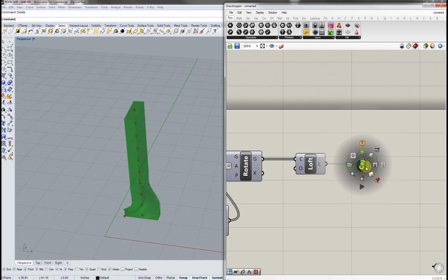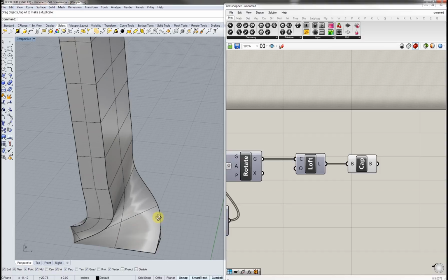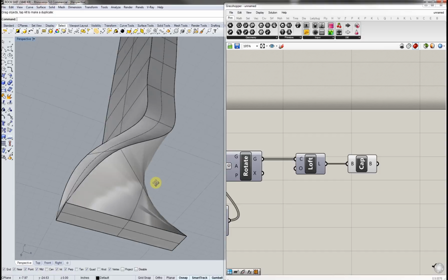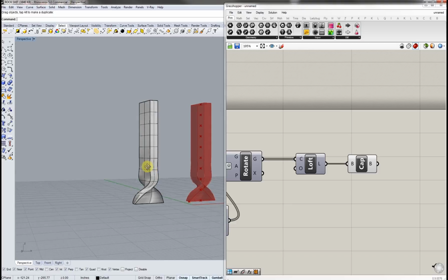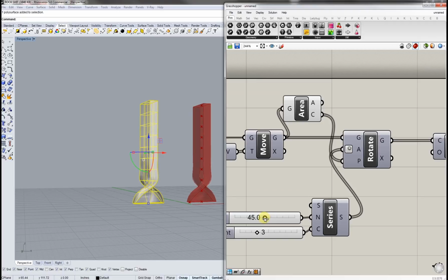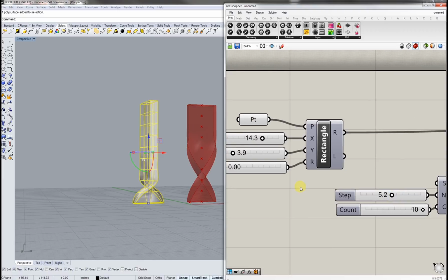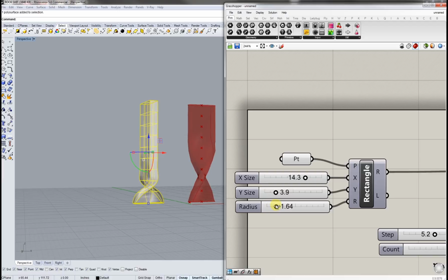Now, if you wanted to select this geometry, obviously it's not real yet. It's not existent, it's just a graphic. So if you wanted to take this geometry and actually have it in Rhino, what you do is either hit any of these plugs and you can get the data, but let's say we wanted the surface. Let's select cap and basically hit spacebar, hover over this egg, and it'll say bake. Basically, that gives us Rhino geometry. Right there.